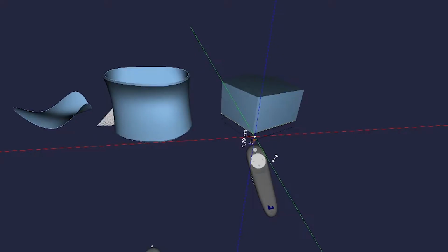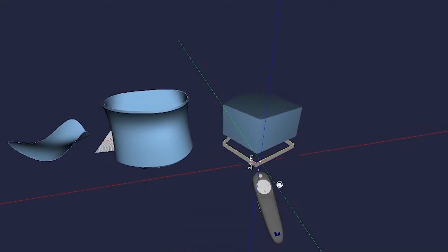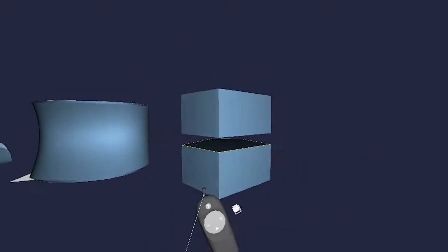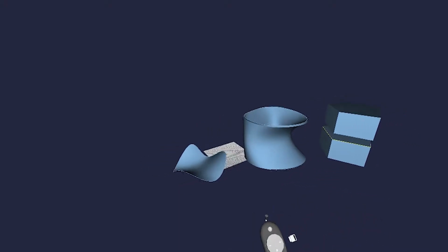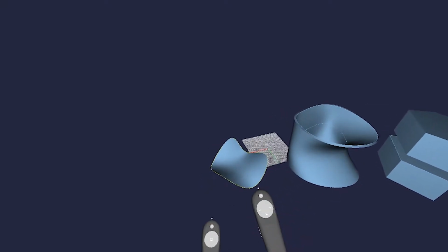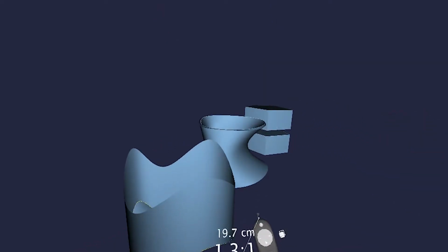So again, I'm going to try copying the same curve down and then extruding downwards, creating another solid. This starts to give you the sense of how fast you can begin modeling and creating solids using the same curves and similar commands. Now, if you use a curve that is not planar, like the curve that we used for this patch command, you'll notice when you extrude it, it becomes a wall or a surface and not a solid.